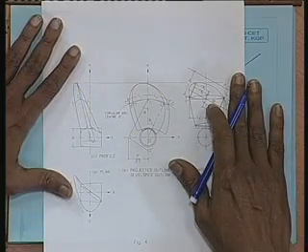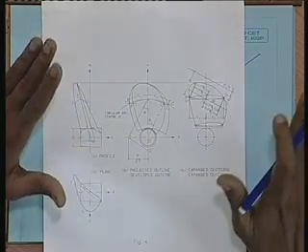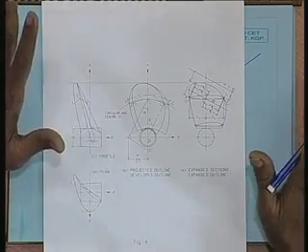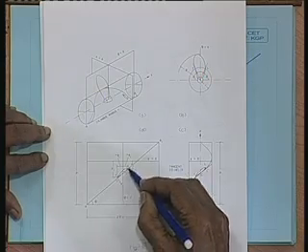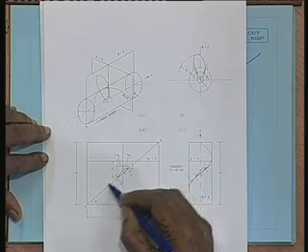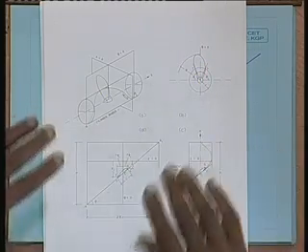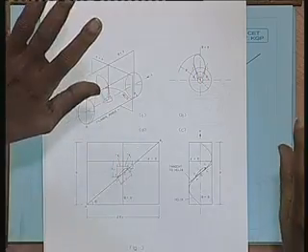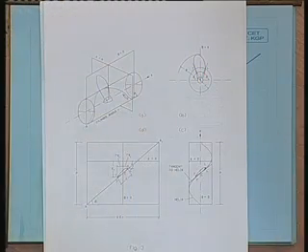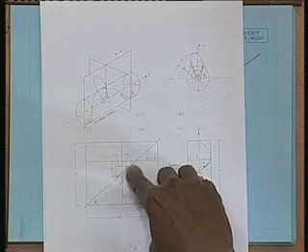So, the most difficult part of propeller geometry is representing it diagrammatically, showing its various features. If I bring back this diagram again, this section shown here is what is called an expanded section. That is, if I expand the helix, this is how the section would look.